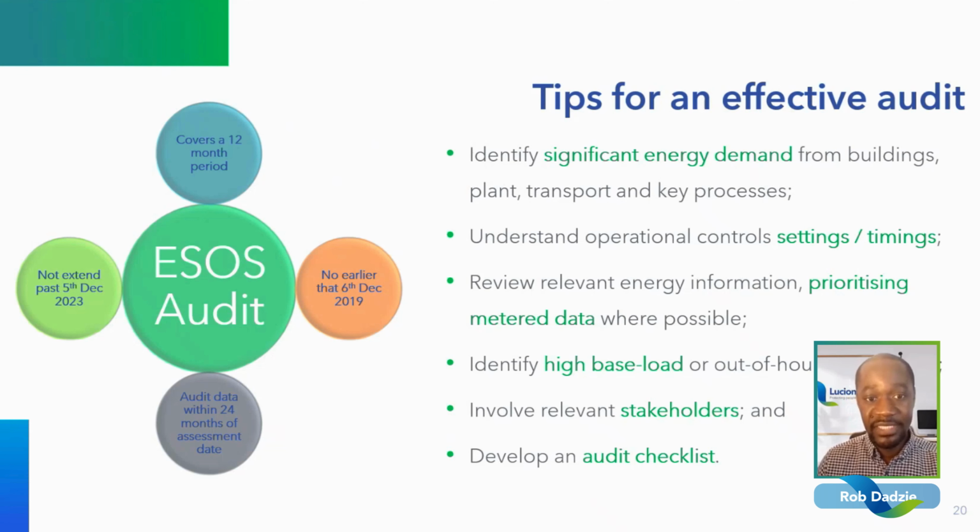Where possible, prioritize metered data, actual data, over bills and estimates. Identify high base loads and out of hours energy. Those two profiles should look very different. Out of hours, you should see a decrease in energy consumption. We've typically done cooling degree day analysis for clients where we might say, okay, in the winter, what is the cooling demand, and are you benefiting from free cooling scenarios, or are you cooling excessively when temperatures outside don't require it? In reverse, are you heating excessively when it's summer and you don't need it?